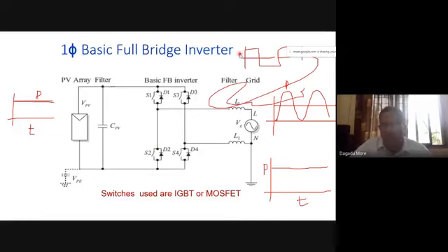On the AC side, we are injecting a constant, square wave type current into the grid with this system, let us assume. And our power requirement may be varying with respect to time. In that case, to balance the power, we require a filter capacitor.